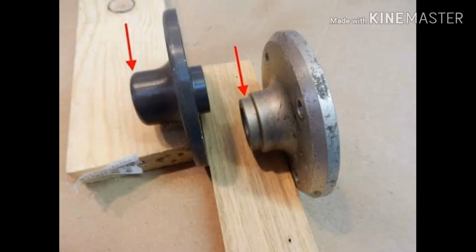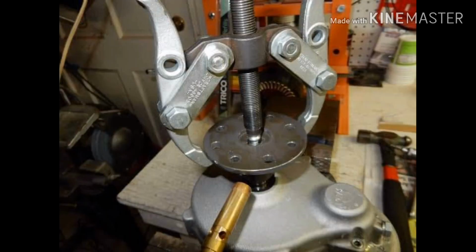Propeller corrosion can be particularly insidious, occurring on the surface of the blade itself or hidden within the propeller hub. Corrosion can also occur on the surface of the airplane if the protective layer of paint has been damaged or removed.